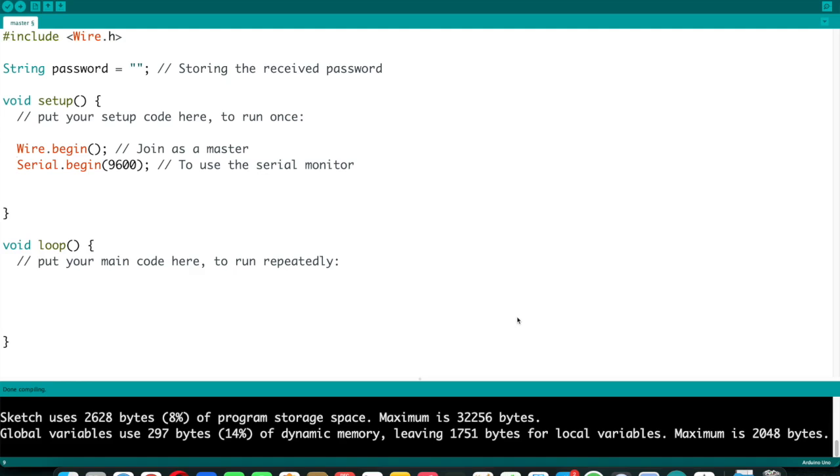However, since some people will ask what is the line or the wire connecting the laptop with the Arduino board, it is the USB cable. Okay, and the USB cable uses what? Uses UART. Okay, so this serial.begin is UART, and here it is I2C/TWI. All right, so moving on, here I decided 9600 bits per second, the speed of transmission. We can go into the loop.